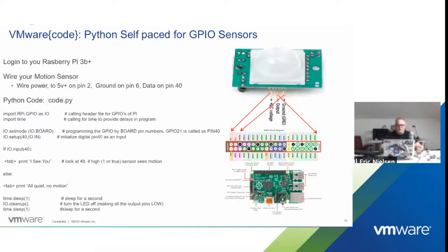So I thought I'd start with some simple code to talk about how I would use my favorite little guy, the motion sensor. Well, I want to first wire it up, and I need to give it ground, power, and voltage. So I look at this and go, okay, I want my red on the first pin, which is pin 1. I want my output, which is my digital out, on pin 2. And then I want ground on my pin 3.